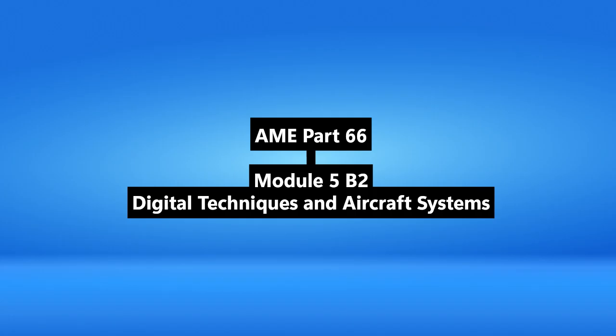Exactly. DO-178C also really strengthened the requirements for traceability, being able to link every requirement down through the design, the code, the tests, and back again. The level of detail required for this tracing gets much higher for the critical DALs. You hear terms like red trace, purple trace, denoting very specific, complete coverage analysis needed for level A. Incredibly rigorous, as it should be.